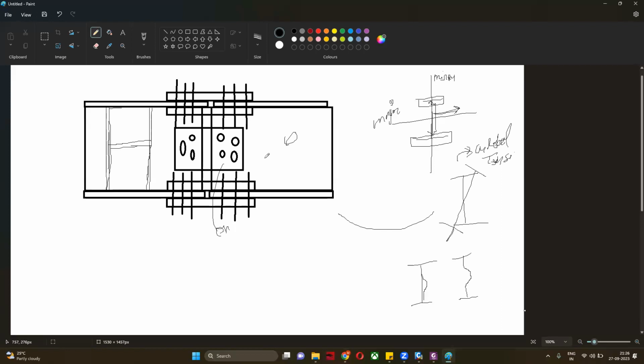Sir, for global buckling, which stiffener, and for this one, which stiffener? Global buckling, you do not require any stiffener. You require strong webs, stiffener, and also your top slab. Our top slab will try to resist our global buckling, and also our bracing and stiffeners will try to block it.